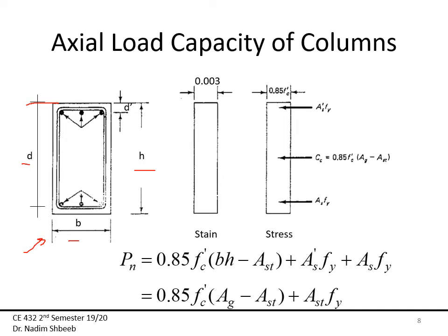Now again, here I'm just dealing with pure axial load, so you say, where's the tension coming from? Well, if there's a moment, then I'm going to have tension, but for now there is no tension, so everything is still under pure compression. But the D still means what it means in flexure, and the D prime as well. I just want you to know that further down the road. For this drawing, I have a pure axial compressive force, which means if this is my centroid, then the load is applied right down in the middle at the centroid.